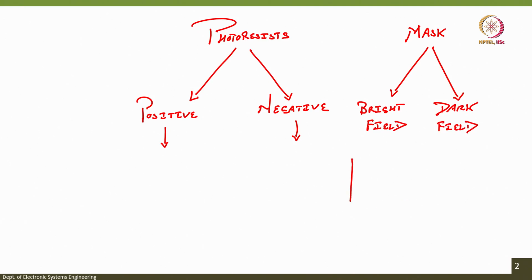The material is either Fe2O3 on soda lime glass, or it is a chrome mask. So if I have this structure, which is a very simple structure I am drawing, a square box on the glass, then we have something called mask alignment marks.